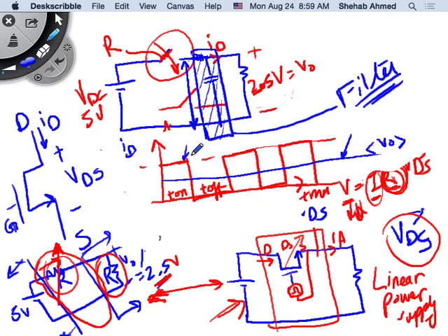I see this nice waveform. It has an average value. I know the average value of a pulsed waveform. If I have T on and T off equal to each other, I know that if this is 5 volts, the average value of it is 2.5 volts. I know that. You can do the Fourier series, or you can find the average value using 1 over the period times the integration of the waveform x of t over the full period. You will get 2.5 volts.